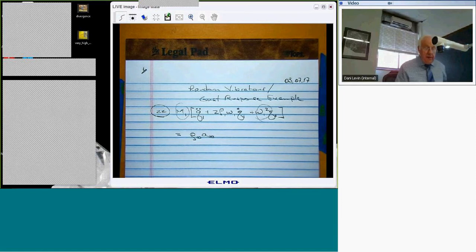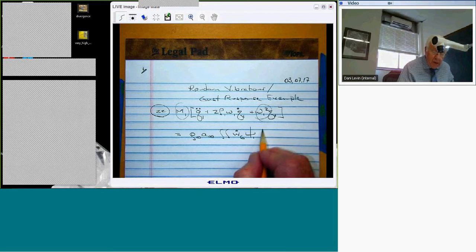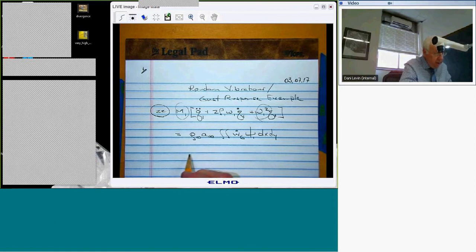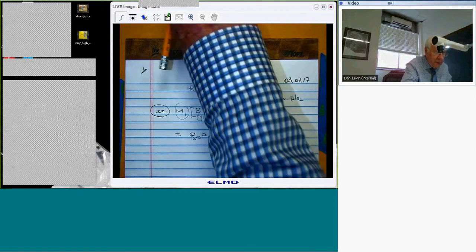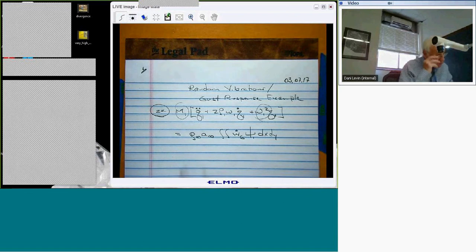And so it's the density of the flow times the speed of sound. And then for the gust term, it's the gust velocity weighted by the mode shape integrated over the wing or the structure. And then there are also contributions to the aerodynamics from the motion. And those have the following form. Again, it's the same coefficient, but there are actually two terms.